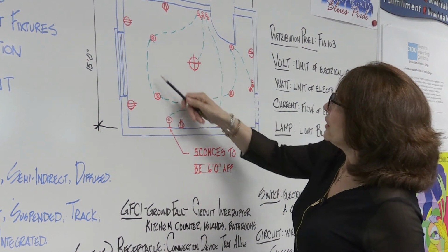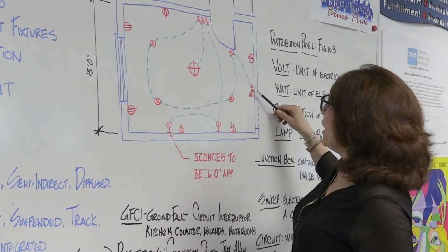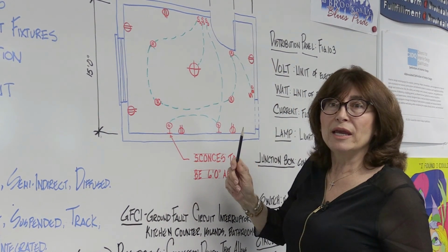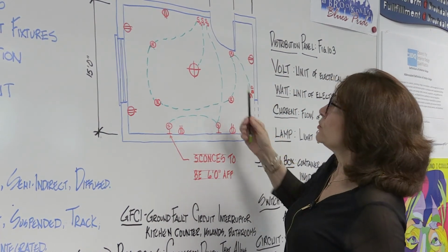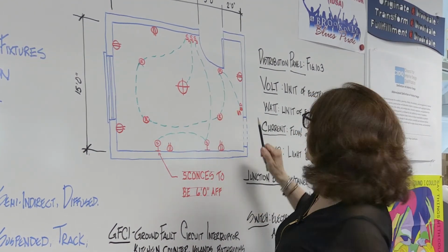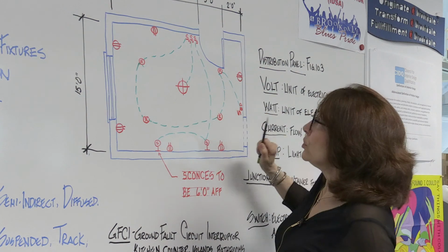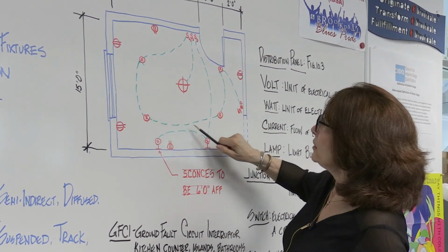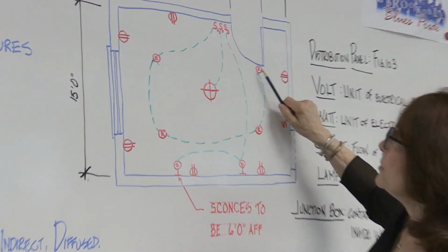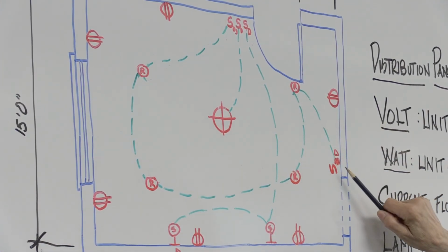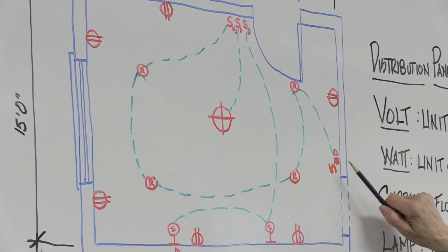The other thing that I did for the recessed was I wanted to be able to turn them on and off from 2 different locations. That's a 3-way switch, and it's identified by an SD3, which will work in 2 locations. So I have the wiring, okay, the green is the wiring, going from one switch to the fixtures and then to my other switch.